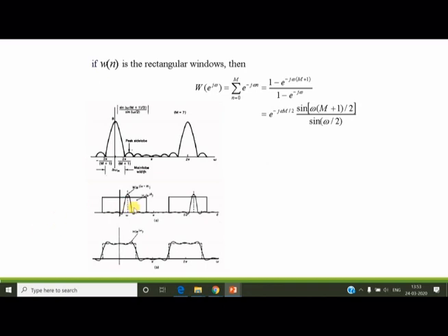Following the usual procedure in convolution, as one of the segments is kept constant, the other segment keeps shifting, and during the shift there is a multiplication and finally the addition between the terms. But remember that this convolution is taking place in the frequency domain. Ultimately, the result is shown in the final graph, where we see the frequency response H of omega resulting as shown by the arrow.